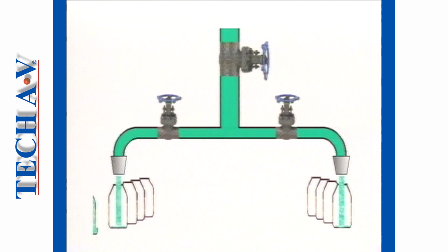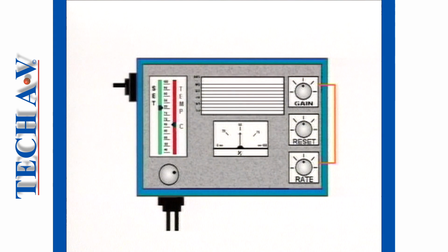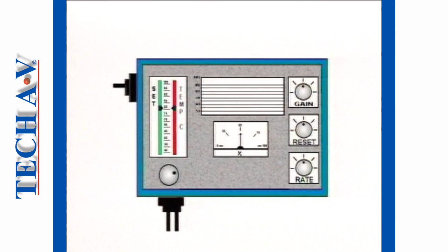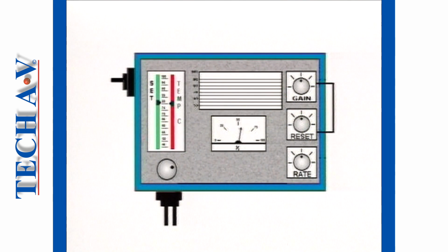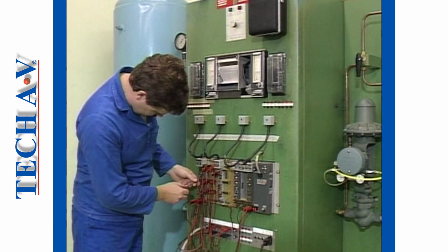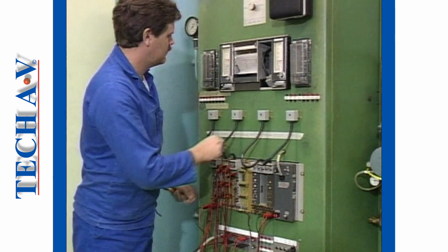A load change occurs as one of the bottling lines is brought back online. The temperature drops due to the sudden load increase, and the derivative action unit responds by signaling the proportional action unit to give additional but temporary valve opening. The product temperature begins to stabilize and levels off, hence the derivative unit action will stop. Once more, the valve is positioned under the control of proportional and integral action. Our controller now has three modes, having added the derivative action unit.